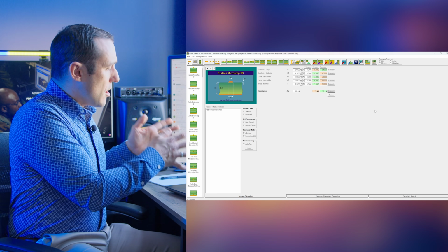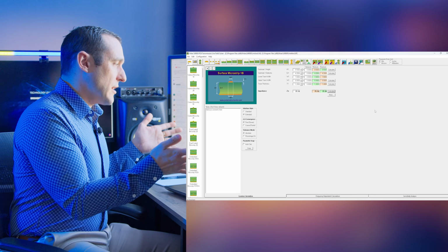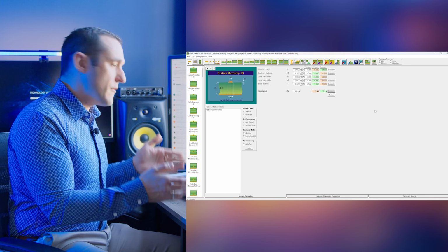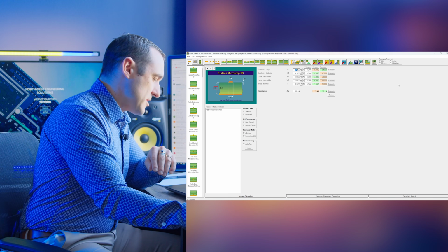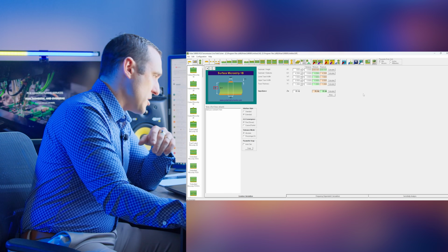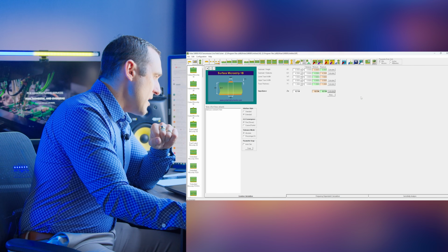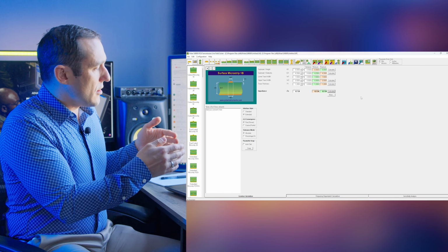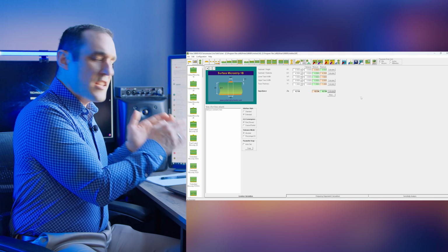So here you can see on screen we have a surface microstrip pulled up, and this tool allows you to calculate the impedance of this surface microstrip. You can see here that we have an entry for the substrate thickness. If I just change the substrate thickness to 6 mil, for example, I hit calculate. You see here it uses its internal model to then calculate what is the lossless impedance of this microstrip.